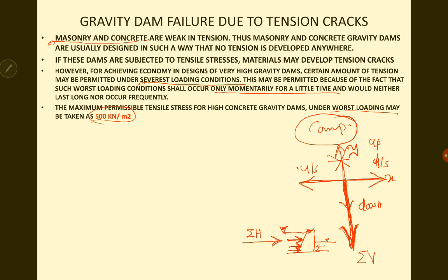Now, if the dam is empty, there may not be any tailwater, but if it is there, or if there are some other forces acting in the upstream direction, then the horizontal force sigma h can be in the upstream direction also. That is the dam empty condition.